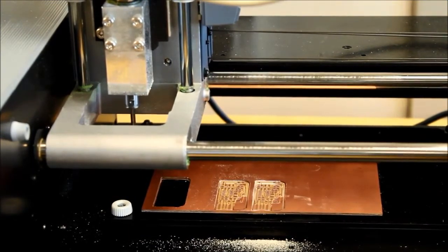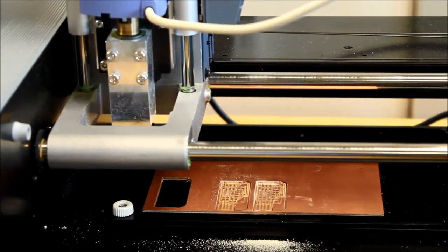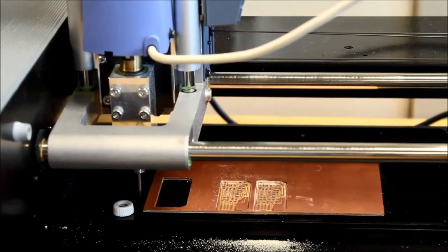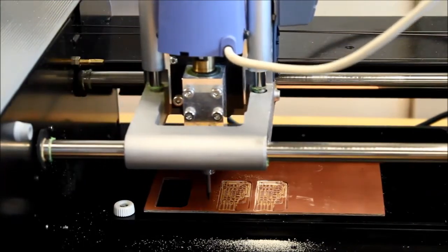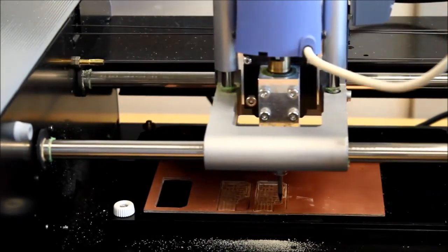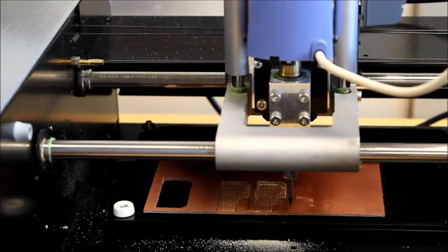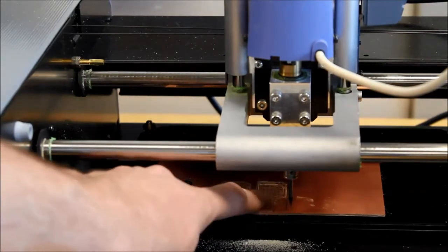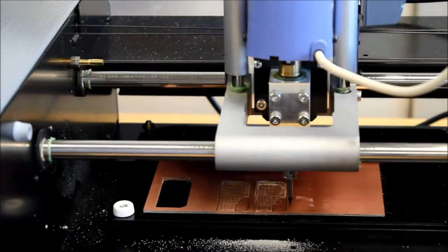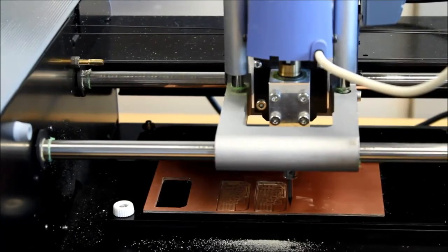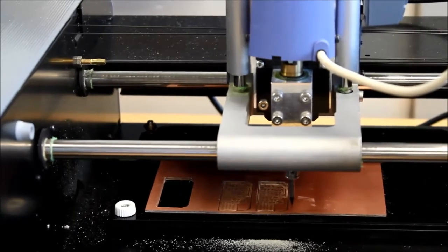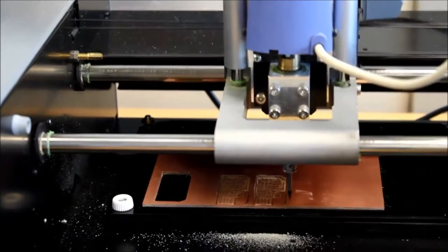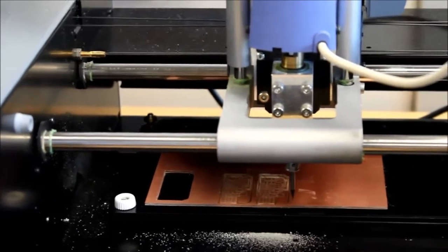So I click this. It's going to drop the drill bit in the Z-axis just a little, and then it's going to move to my XY position. What I'm looking for at this point is to make sure that this bit is going to clear my previous milled spots. I want to cut a fresh, clean PCB. So I've done that. Now I'm going to set up the exact height for the Z-axis.